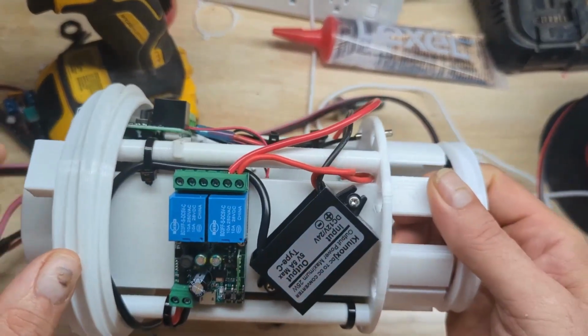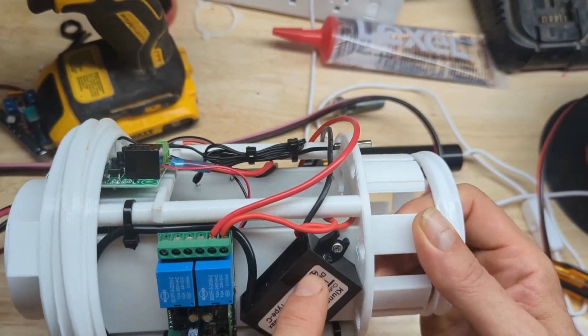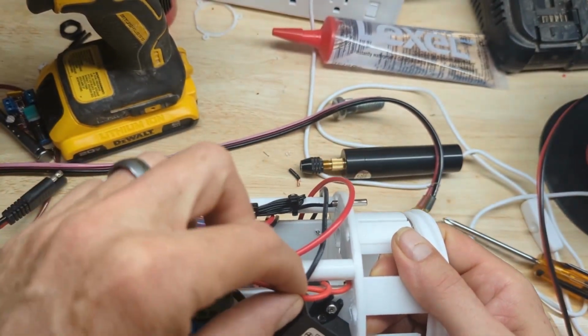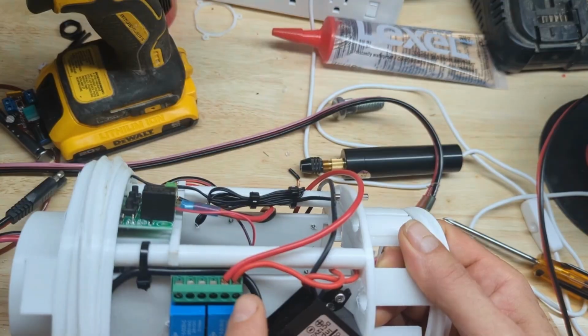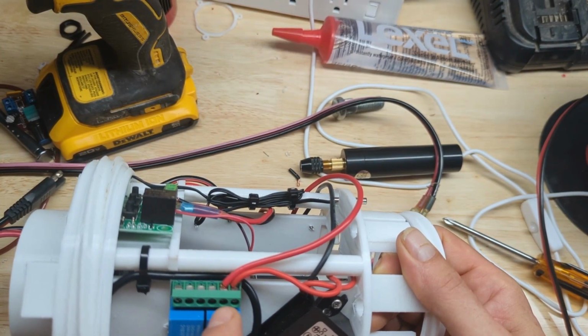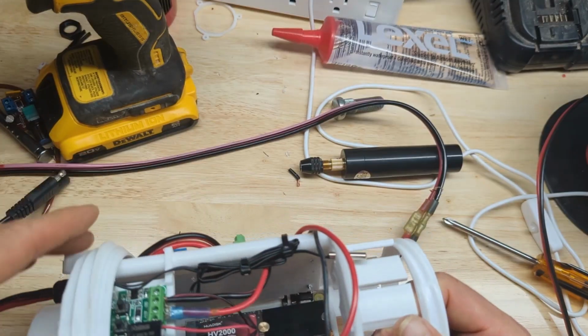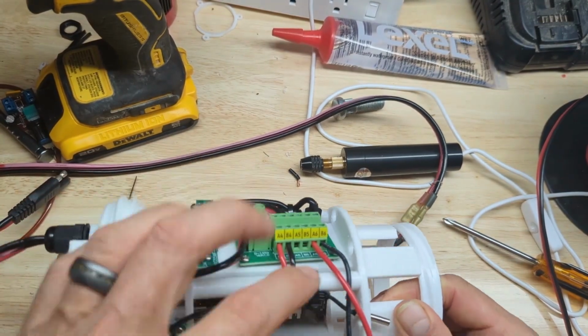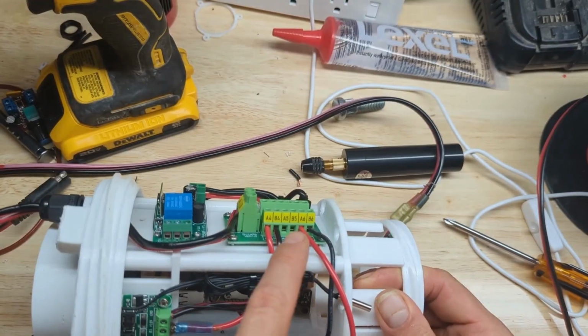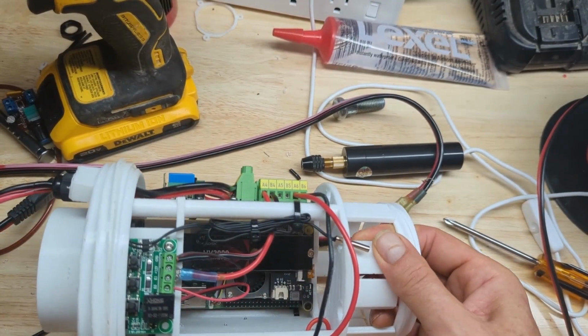Okay, so that's wired up now. So this is our power block that will power the USB-C on the Raspberry Pi. You see this first lead coming off of it is going into the very first outlet, and the second lead, also a positive cable, is going over to our power block. Of course, the ground coming off of this is also going straight to the power block, because obviously it needs a ground and a positive.